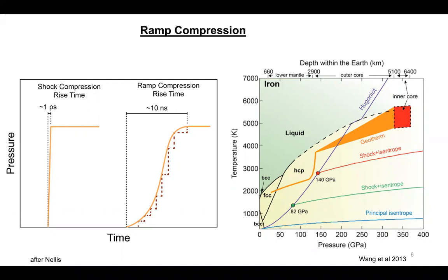A way to visualize this, as indicated by the dashed curve, is that it's akin to breaking the compression wave into a series of small shocks. Each shock achieves a much smaller volume change or compression, and so the shock heating and entropy creation is reduced. So a greater fraction of the energy goes into PdV compression work.